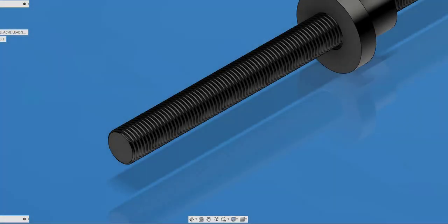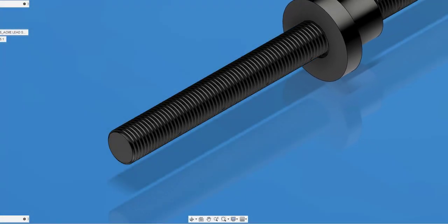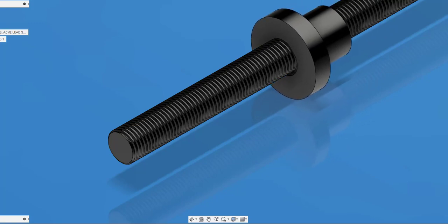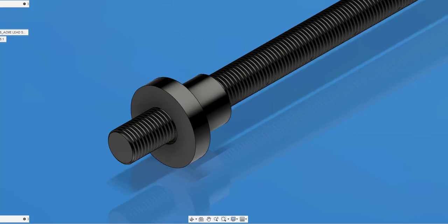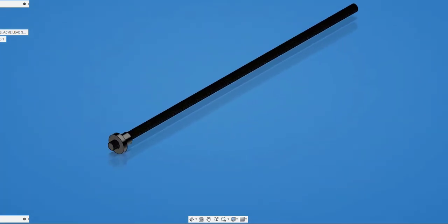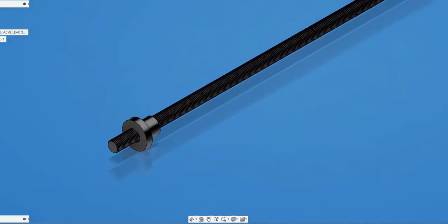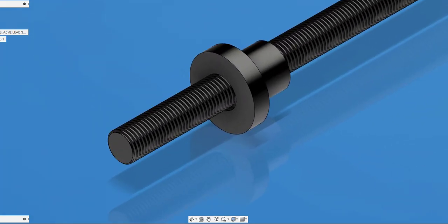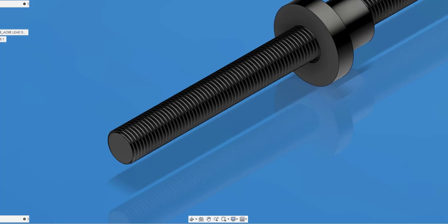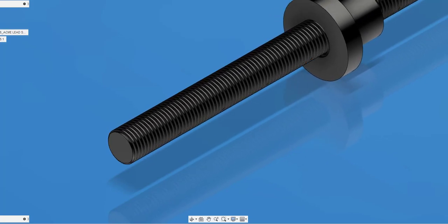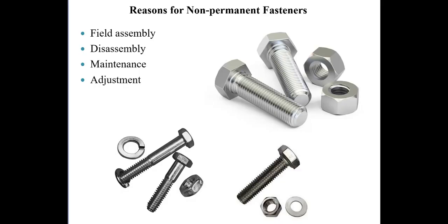The speed with which we move depends upon the rotational speed of the shaft and the pitch of the threads, and the amount of force we can generate on the collar is influenced by the torque we apply. This is all related to what we're going to talk about with bolted connections as well. With bolts, the amount of torque you supply determines the preload in the bolt and the compression of the bolted connection. It's likely not obvious that there's a simple relationship between our understanding of power screws and of bolts and nuts, but there is, and we'll get to it in a short bit.